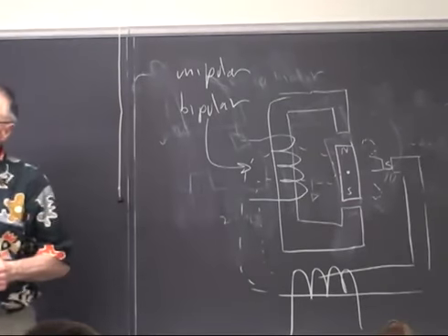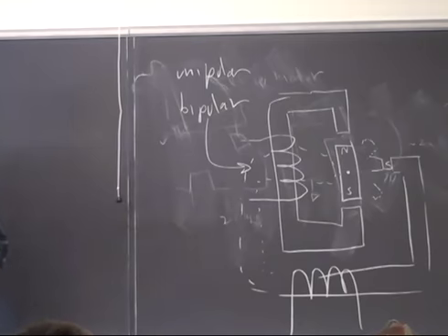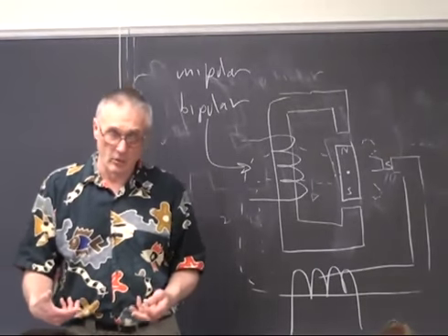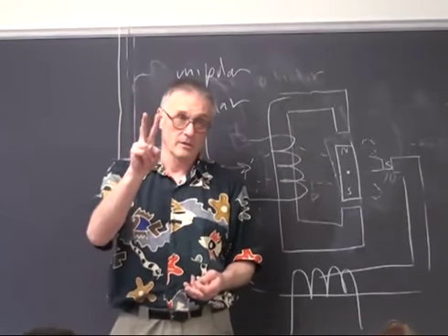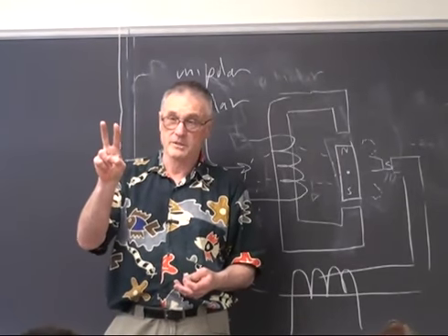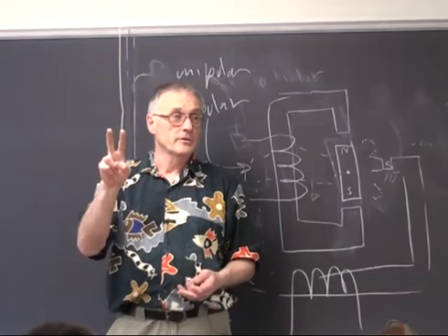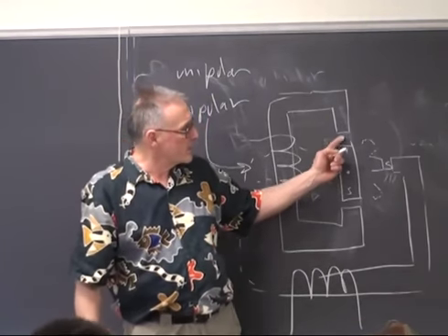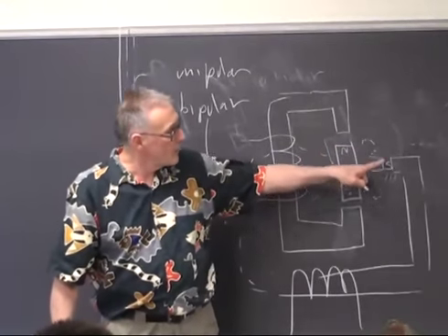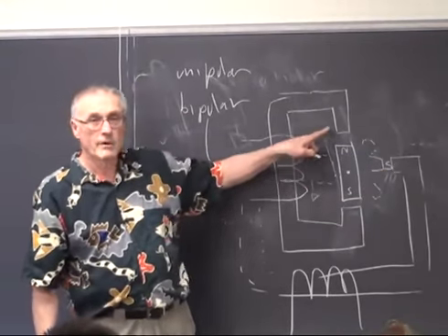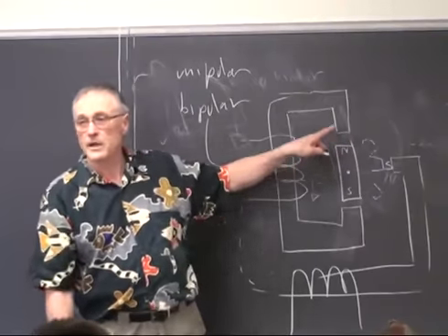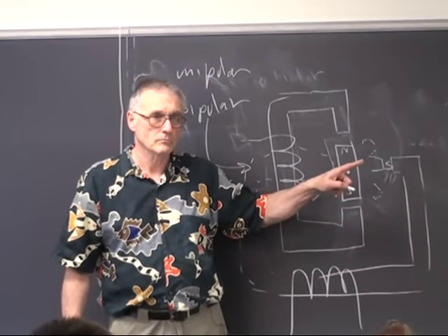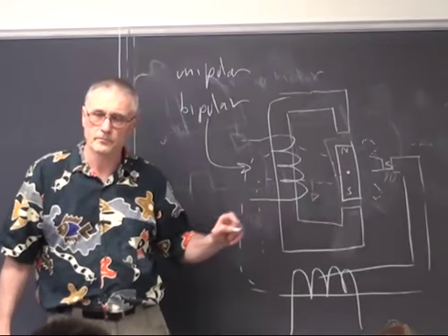So the challenge here then is to produce an overlap pulse sequence on two coils to move the motor in the direction you want, by causing the south pole to move either clockwise or counterclockwise around these pole pieces. Any questions?